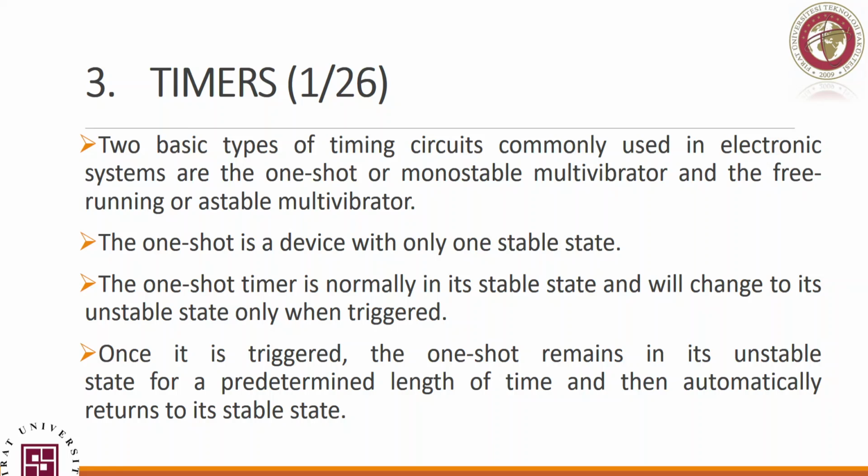We have the one we refer to as one shot, and as the name indicates, it's a monostable multivibrator. That means it has its own triggering time, then back again to zero, then we trigger it to high, back again to zero. It's not exactly bouncing between two levels based on a certain period. Rather, it depends on an outside exciter, or it needs an excitement from outside.